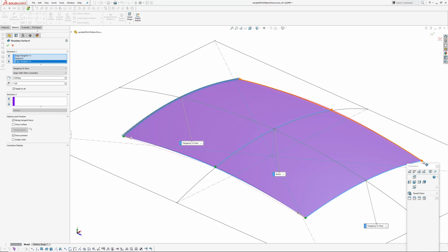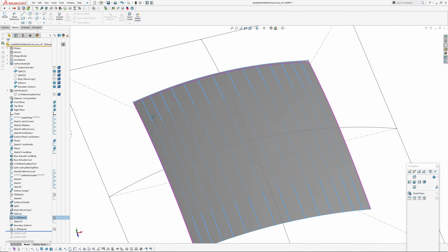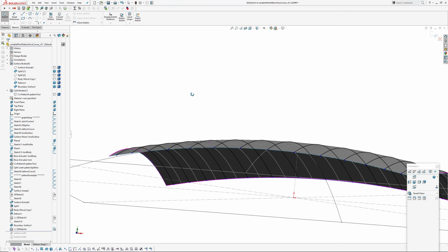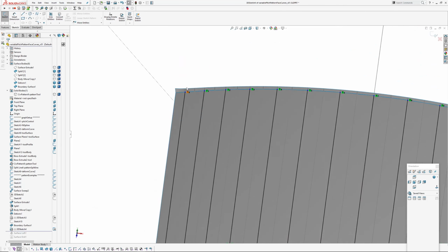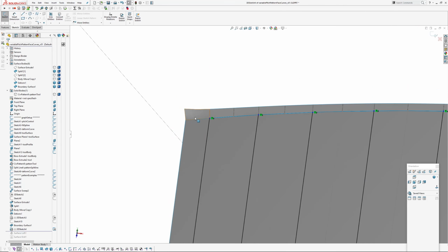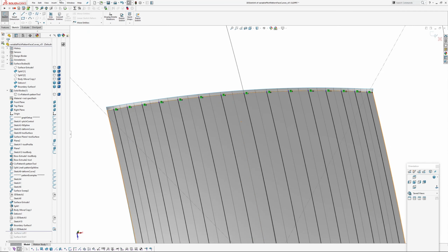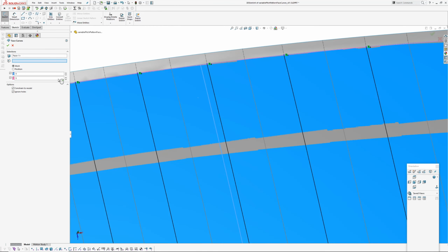So at this end it runs down to being tangent. Okay, and now I've just repeated this face curve thing, except I've done that with the new target surface. I've picked the new surface, like the peak surface. So you can see these curves are above these ones. And I've picked every second one again. It's stepped, I'm stepped out by one. So again, insert face curves, pick surface.